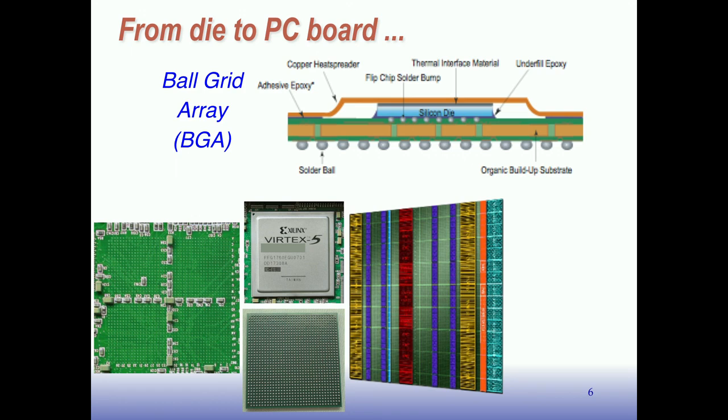Remember, when this is running, it's burning power, and the power generates heat, and the heat has to go somewhere. So either there'll be a heat sink here, which is fins that stick up in the air and help radiate the heat, or sometimes there's even a fan. You've seen this on CPUs, a fan right on the package to draw cold air in and dissipate the heat with the air. What else? I guess that's it.